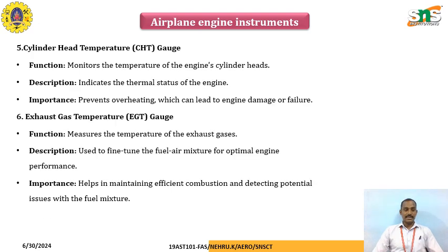Next one is the cylinder head temperature gauge. This helps to monitor the temperature of the engine cylinder head, indicating the thermal state of the engine. It prevents overheating, which can lead to engine damage or failure. Coming to the next one, the exhaust gas temperature gauge. Similar to how the air is measured at the inlet, it has to be measured at the outlet also.